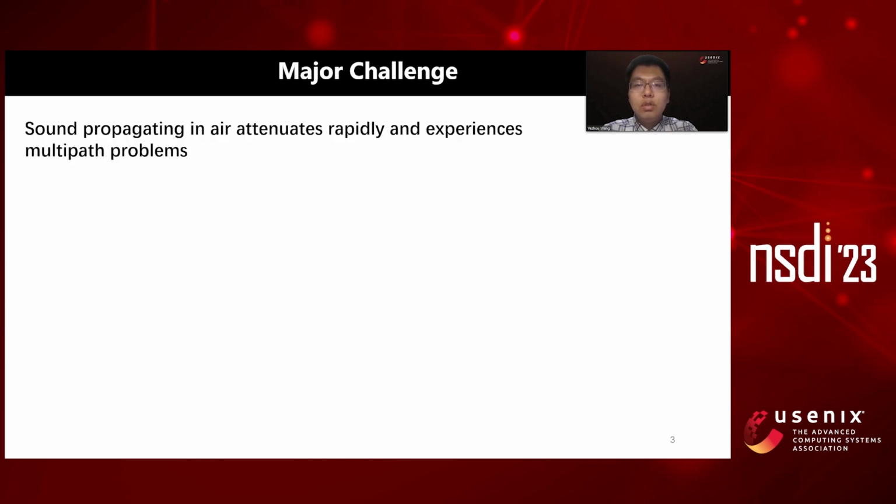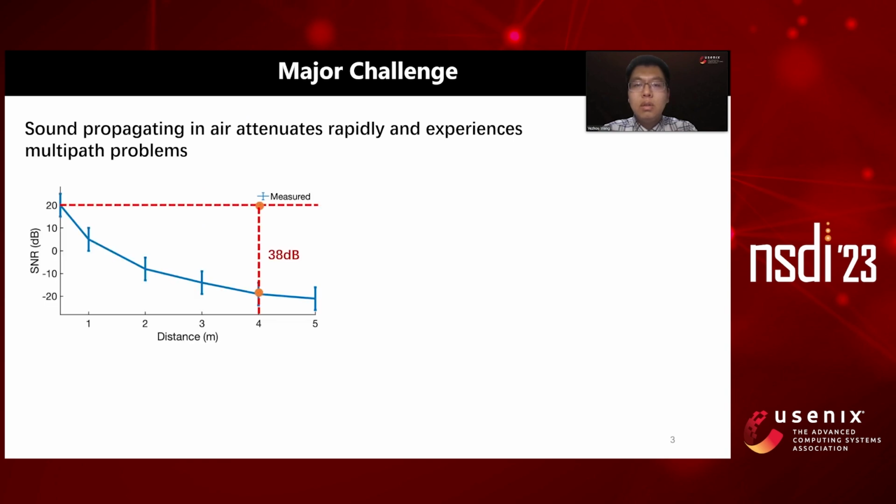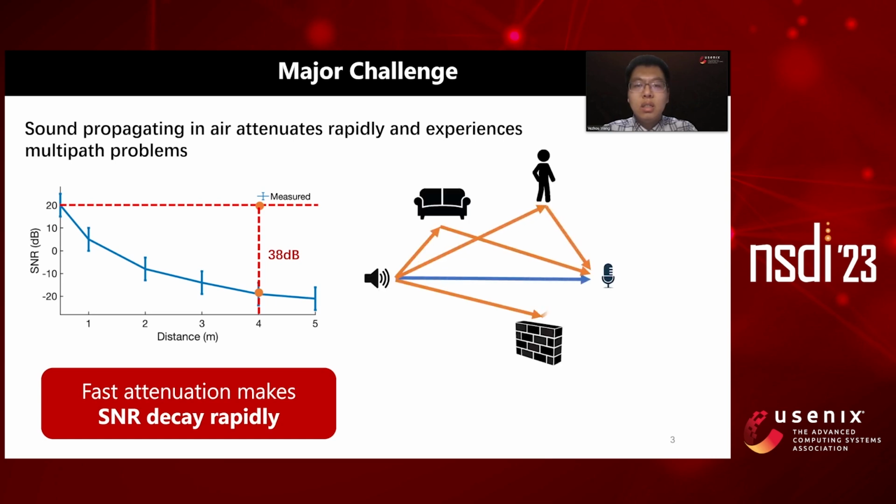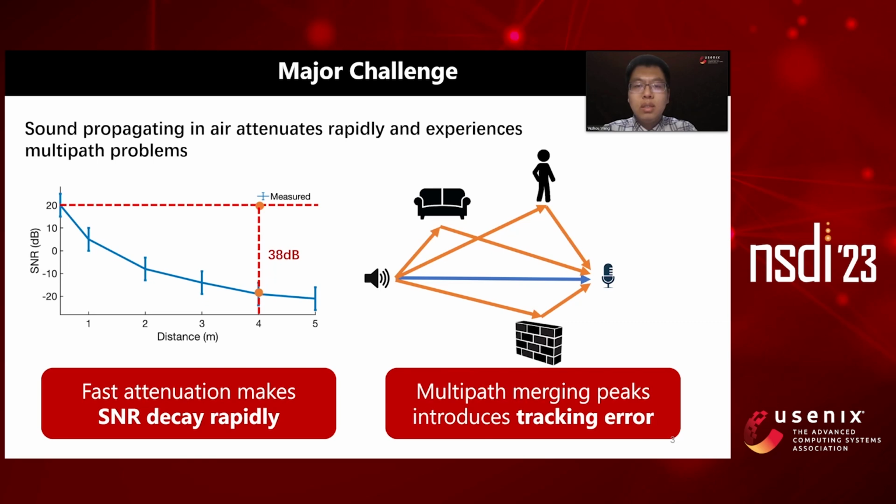However, there are two major challenges for acoustic-based applications. First, the signal attenuates with the square of distance in free space, which makes the SNR decay rapidly. Second, considering a real-world scenario, the reflection from objects in the environment causes the multipath problem. The presence of multipath introduces merged peaks, which will increase the sensing error.